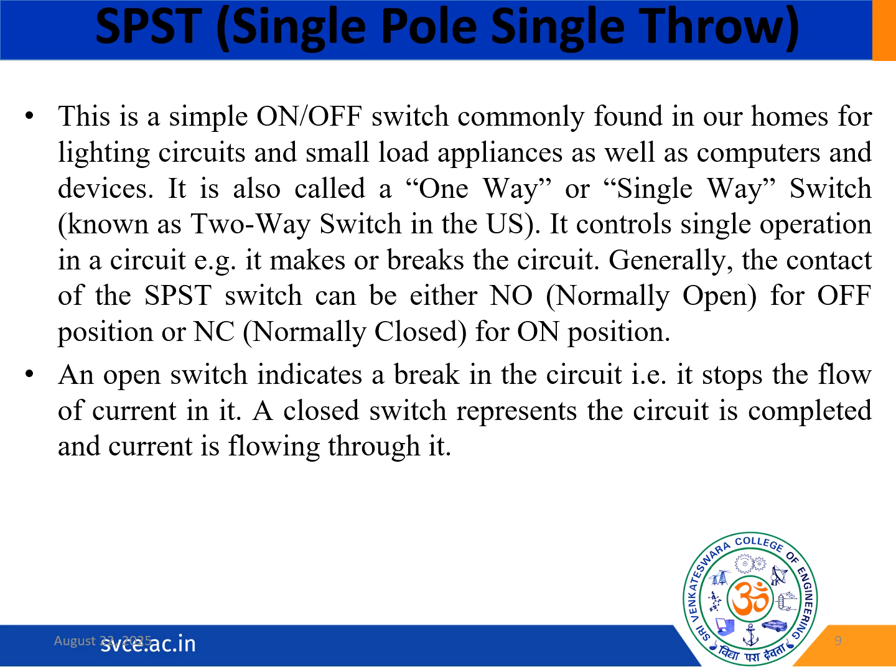Considering the features, it is very simple, ideal for basic on and off control. The design is very compact, often used in small devices or panels. Considering the versatility of SPST, it is available in toggle, rocker, push button, and slide formats. Some common applications are LED control circuits. These switches are very common in power switches for appliances, DIY electronics and prototyping, and we can also use them in automotive and industrial panels.